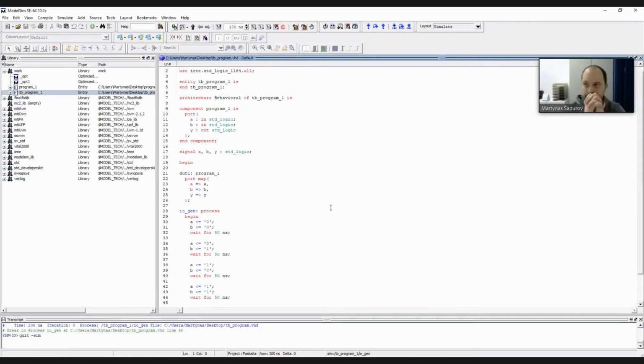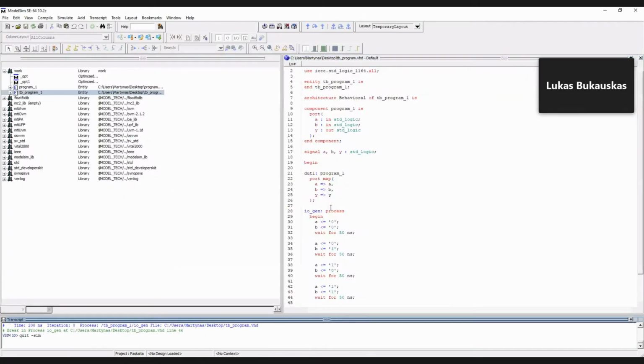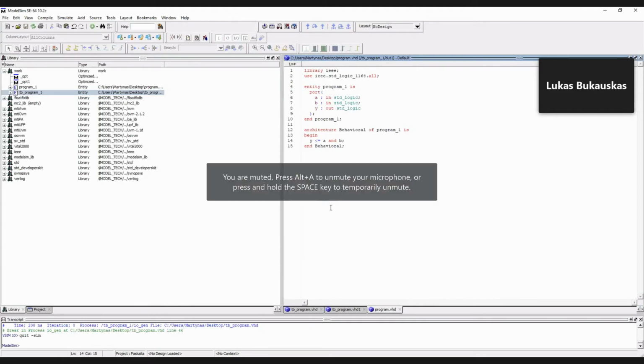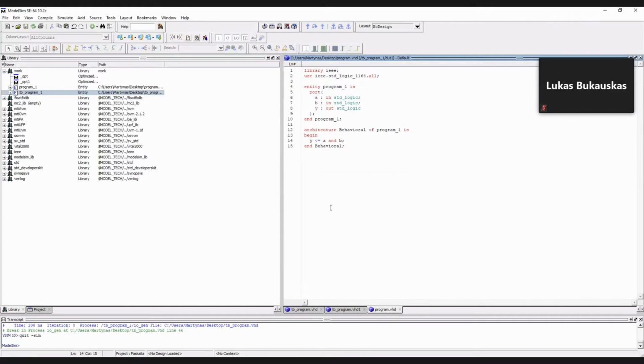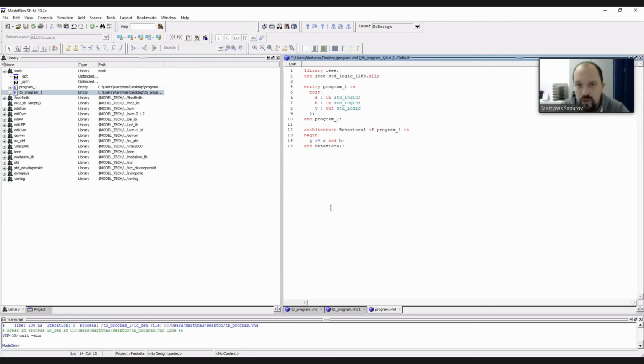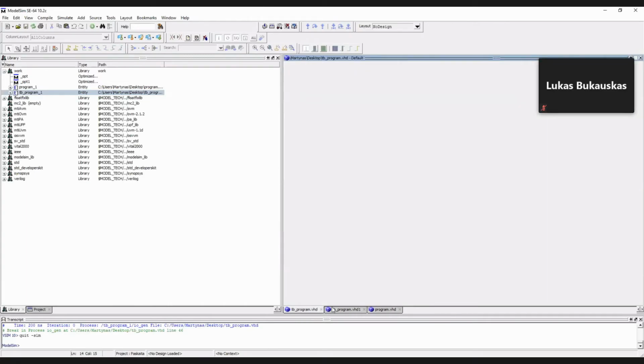All right, questions? I tried doing the same as you did, but I'm getting an error loading design. So somewhere you probably made a mistake. It compiled everything correctly, but it doesn't simulate. It says that I should go to the website and update my version, even though it's the newest one. I think that usually problems occur when you have a very long path. This software doesn't like long paths at all. It likes when the path is short, directly on the C drive somewhere. Okay, I'll check.